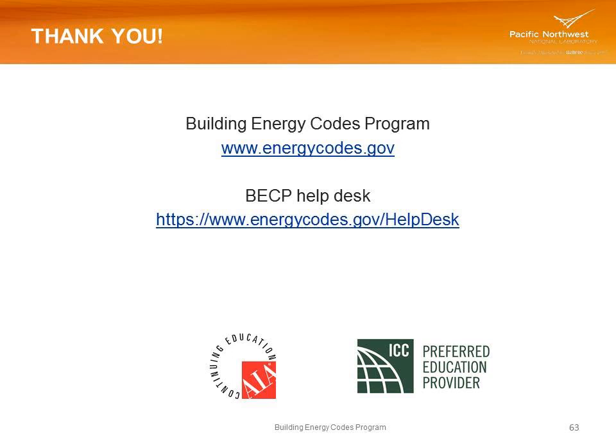So for VAV systems that can only reheat 30% of the air, what about the difference, or what about for a constant volume unit? Well, constant volume units are going to become less and less allowable. There are still some cases in hospitals in certain areas where they are required, although even hospitals are getting to the point where they can manage pressures between isolation zones with VAV systems.